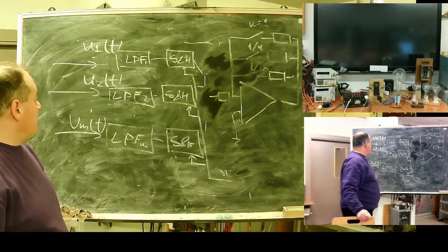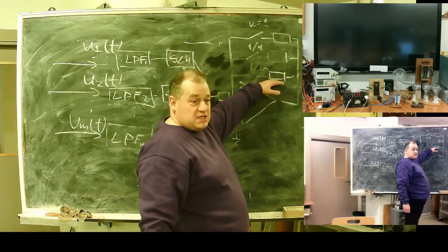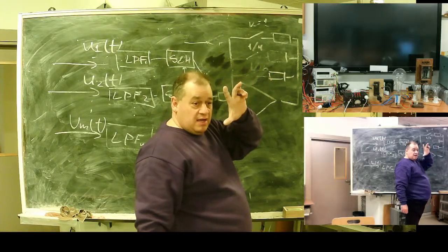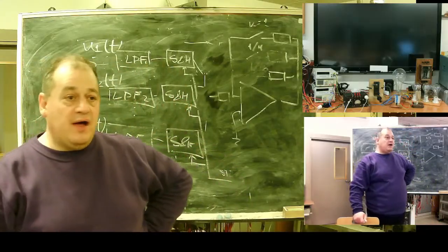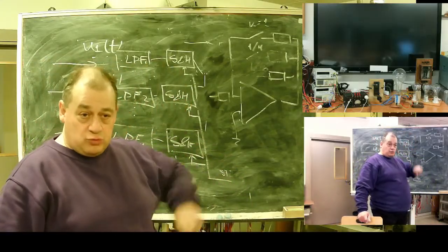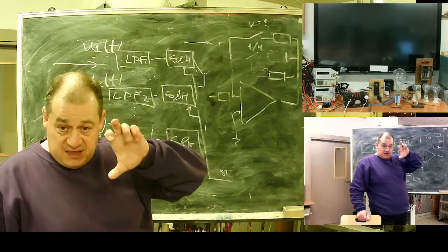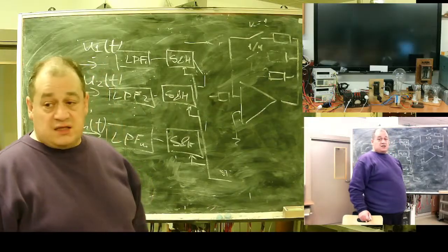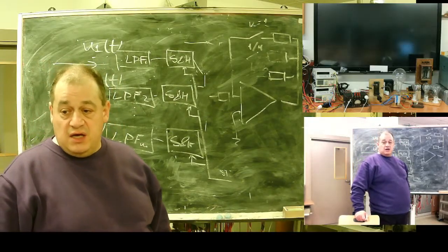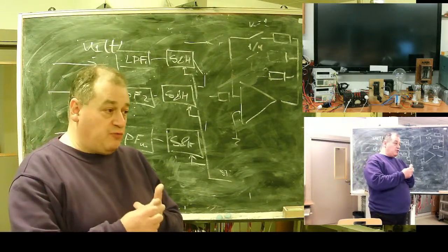First, measurement is taken with 1/16. First, it's a rough estimation, and then second measurement with closest gain to maximum use range of ADC is taken. PGA is controlled by processor. You see what happens? How it works?